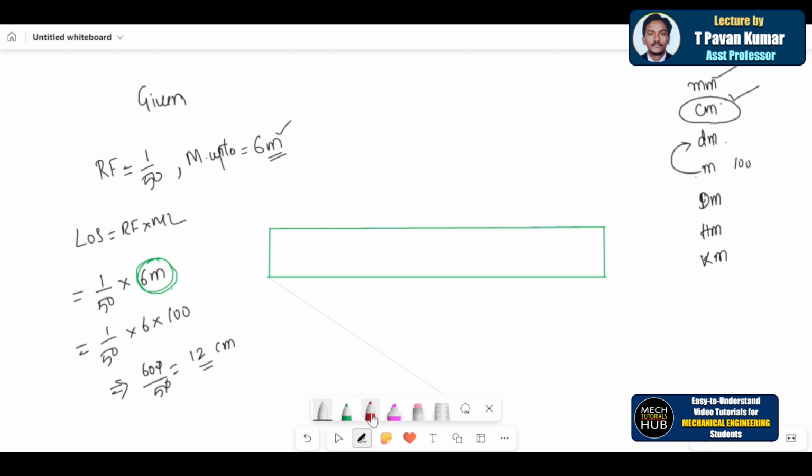Okay, now with the convenient distance 10 mm or 15 mm, divide this length into 6 parts, 1 2 3 4 5 6 parts, and join the last point with the end point of the length of the scale, and try to draw parallel lines. 1, 2, 3. I'm not drawing, it is maybe conventional I'm placing it, but still you people can do properly with your drafter. Alright, these are my divisions. Everything has to be constructed with 2H only.